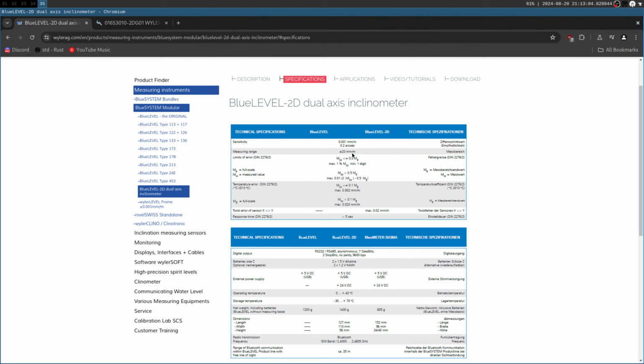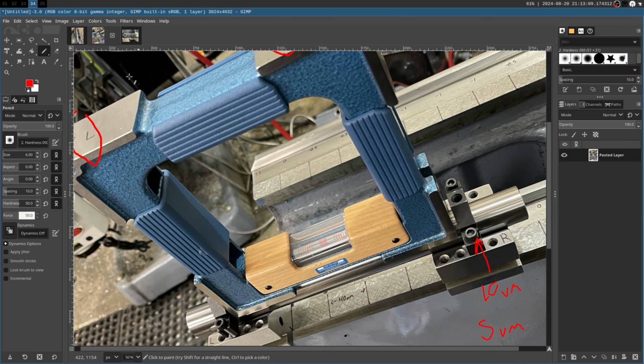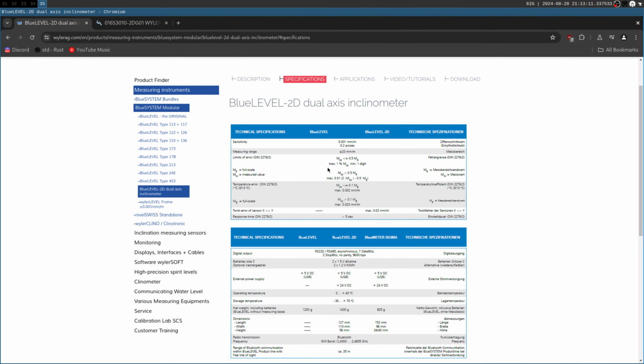It's just more speed, especially when you have complex fixturing for a level like this that you can't transplant to your bootstrapping level. So it's important to have these things. How long do surface plates stay level once calibrated? So stay flat. It's important to note level and flat are different. Level is tangency to gravity, right? Whereas flat is just flatness in any plane.